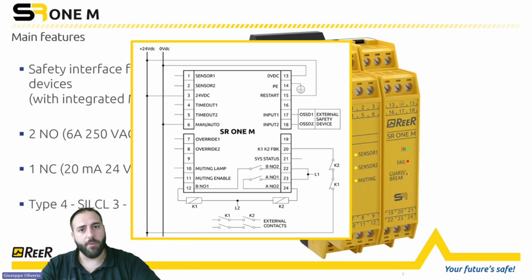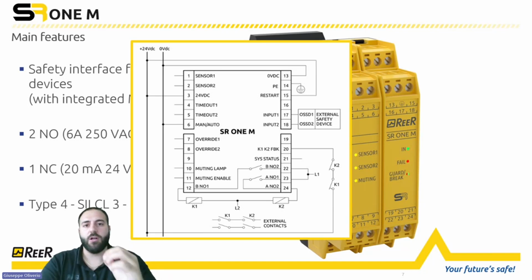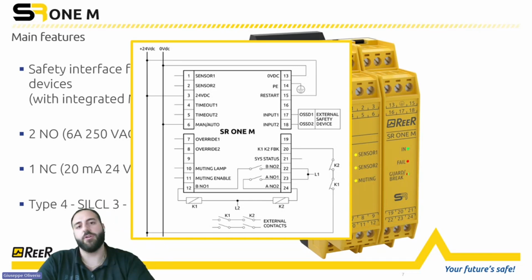The muting enable, we will see the information about the muting enable during the webinar dedicated to the SafeGate, that is our safety light curtains with muting integrated function. But what is important is that in order to consider sensor 1 and sensor 2, you need to wire an external signal to muting enable in order to enable the muting.